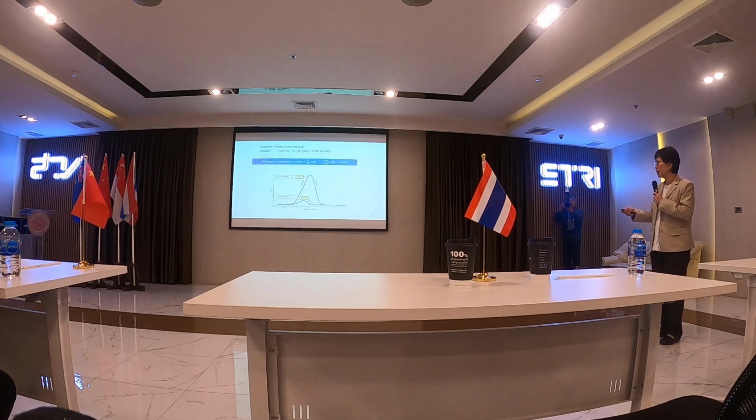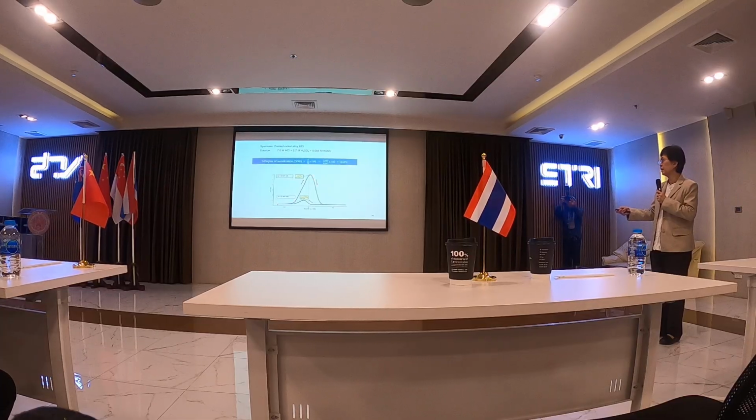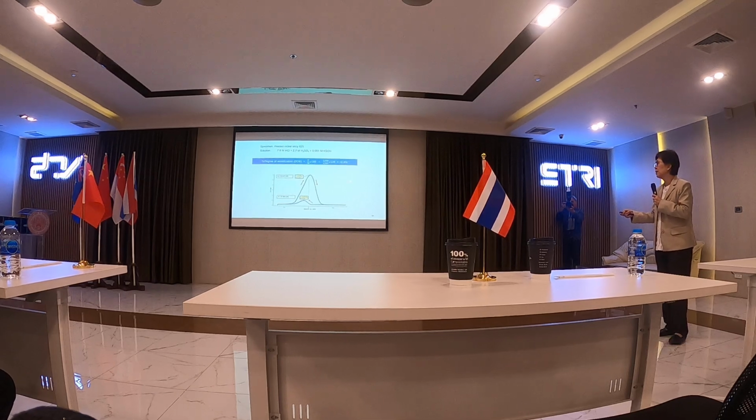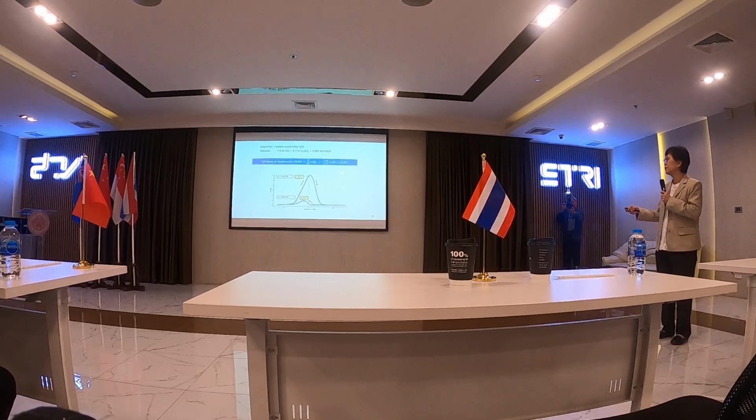We find the corrosion potential and scan forward until it's from the passive film, and then we scan backward again. We use the peak of the backward current, divided by the forward current, multiplied by 100, to get the degree of sensitization percentage. So this one we can say how serious the problem would be.